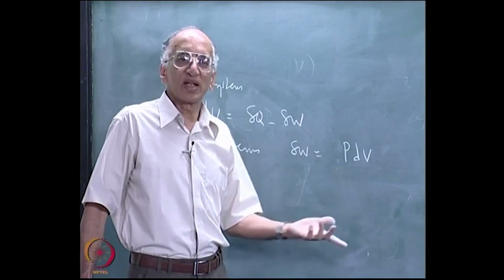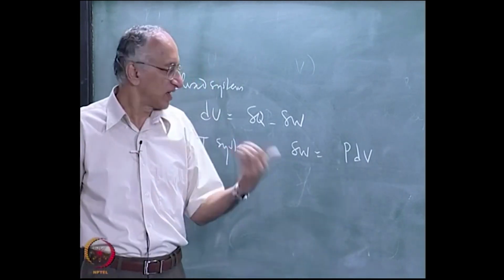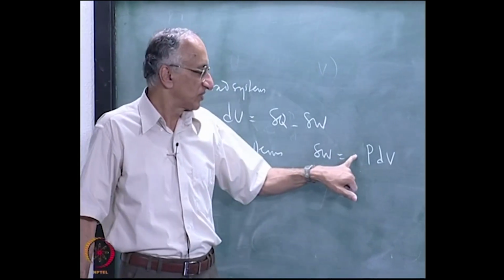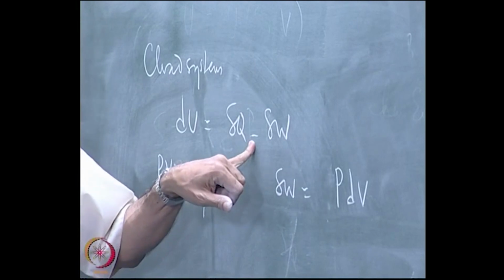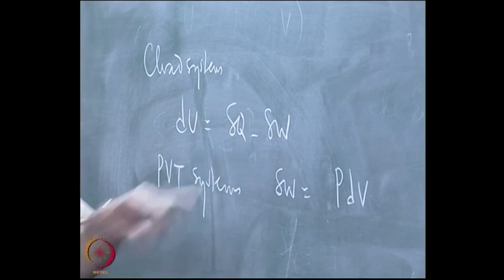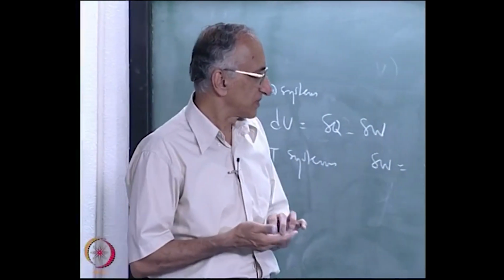So if work is done by the system, it loses energy, so work done on the system is considered positive, so you will find a minus sign here, but those that have a minus sign here will have a plus sign here. So in terms of measurable variables, the equations will be the same. You just use any convention you want, but be consistent, and I am not going to trick you by asking you is it by or on, and you can figure that out by common sense.